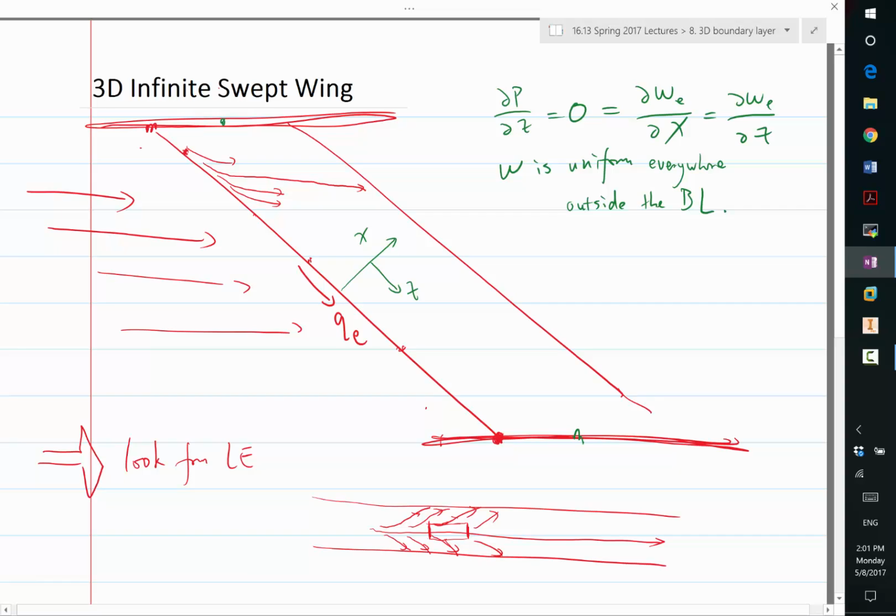So this is true for the equation that doesn't have viscosity. It is true for the velocity just outside the boundary layer. It's also true for velocity far outside the boundary layer. So this is true for anywhere other than in a thin layer near the wall. That is the basis of this special case.